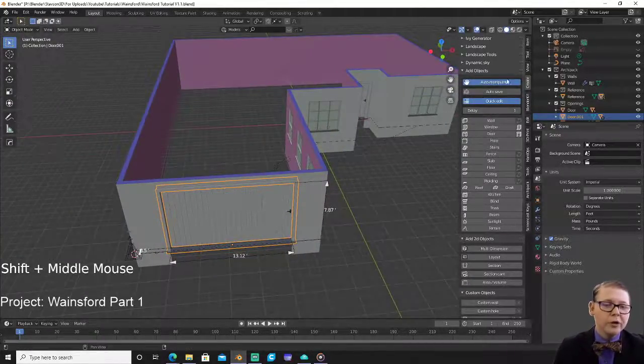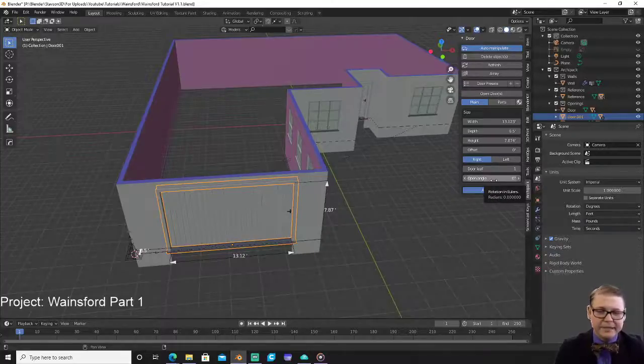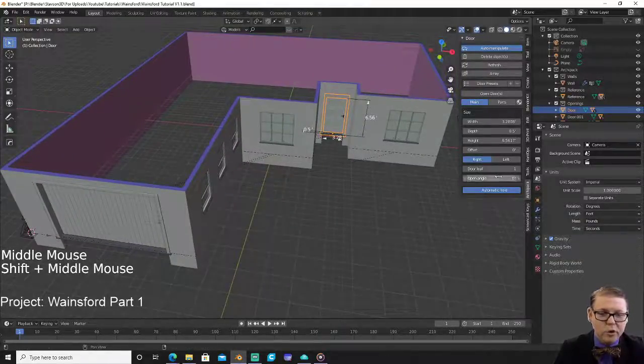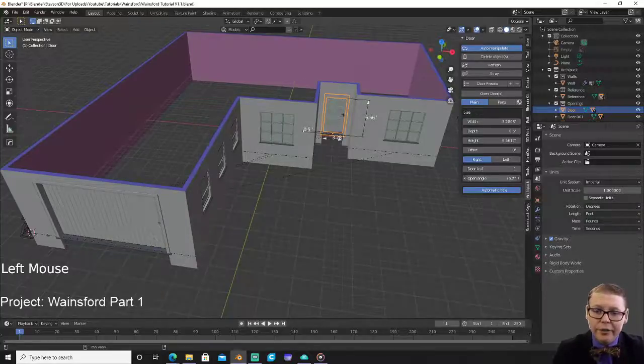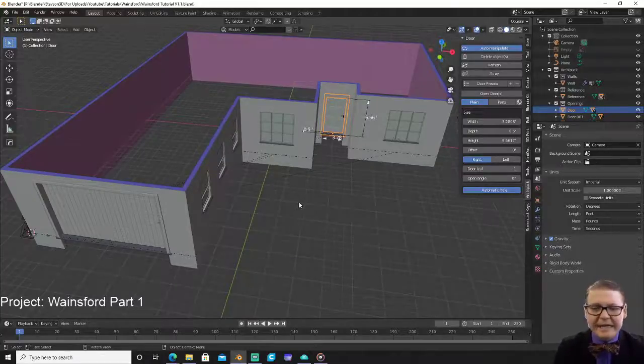let me back up. When you go into the settings of your doors in ArchiPack, you can open your door by a specific angle. So if we want it to seem like somebody left the door open, or maybe we have a character that we've placed in the scene and we're opening the door, then we can open that. Especially for animations, that can be really cool, where if your camera flies in through the front door, you can have the doors open and close as the camera's approaching them. That can be a kind of neat little graphic.